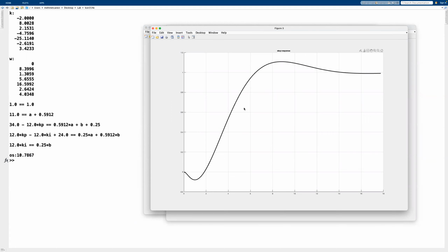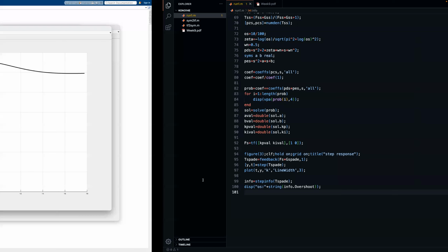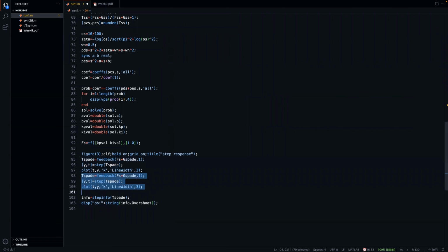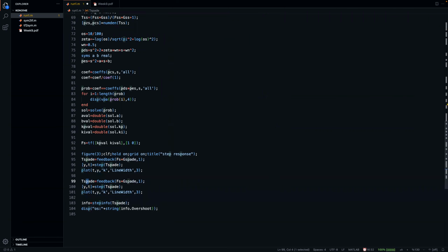It doesn't make sense to look at this and conclude that the system will work, because you didn't try it on the system with delay. You're trying it on the Padé approximation, which you came up with, and it should work, of course, because you're using that transfer function exactly. If we are going to talk about the actual system, what you have to do is, instead of this, you should look at T(s), which is going to be F(s) times G(s).